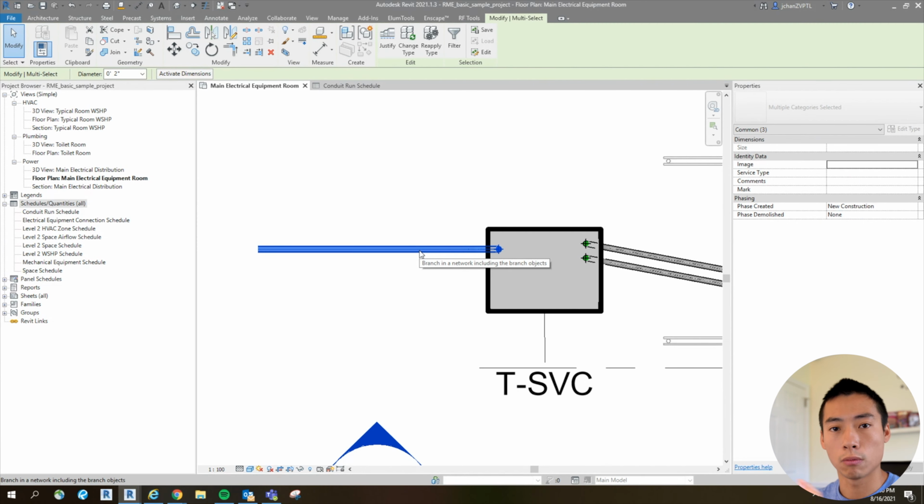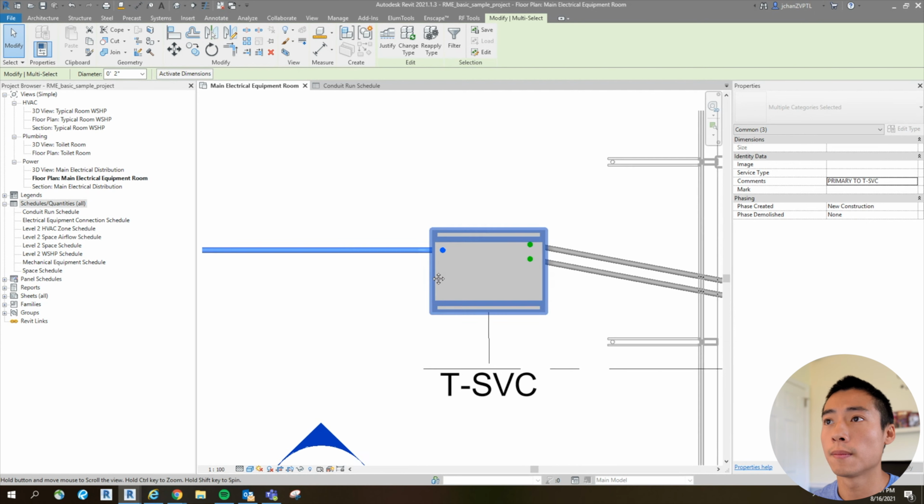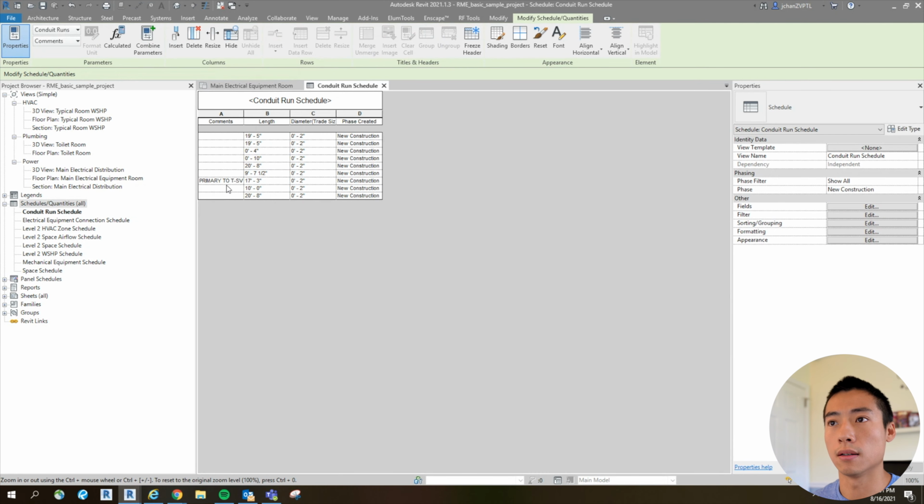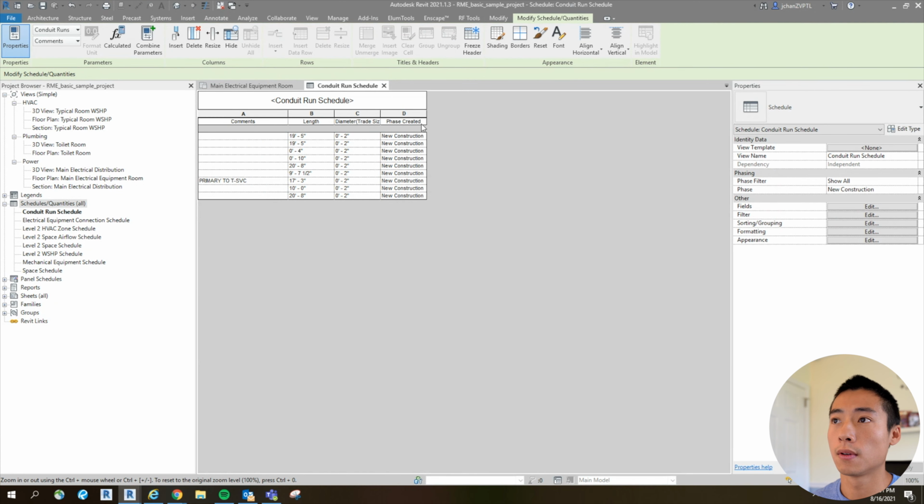Now you have your entire run selected. Go over here to your comments. You can type in primary to T-SVC, primary transformer service, hit apply. Then you can come over here to your schedule. You'll see that it actually starts to populate.